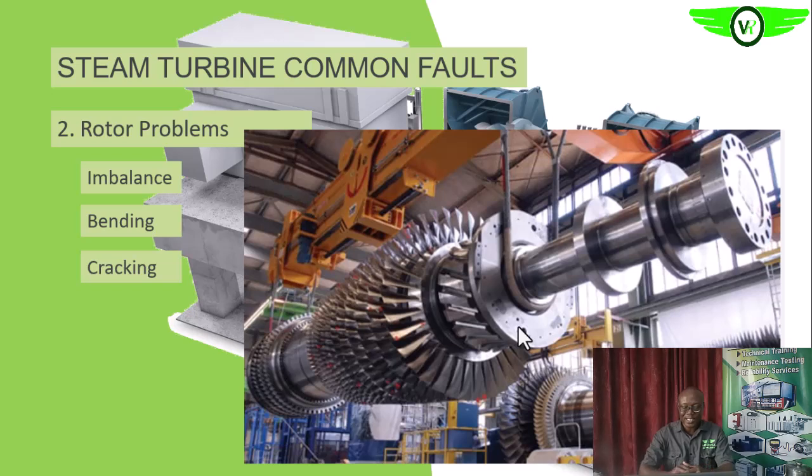So all of these are also unwanted conditions. Then cracks can also happen in the rotor when there is excessive repeated stress on the rotor. Also, what we discussed earlier that affects the turbine blades, erosion and corrosion, can also happen on the rotor, especially on the areas where the steam is passing.